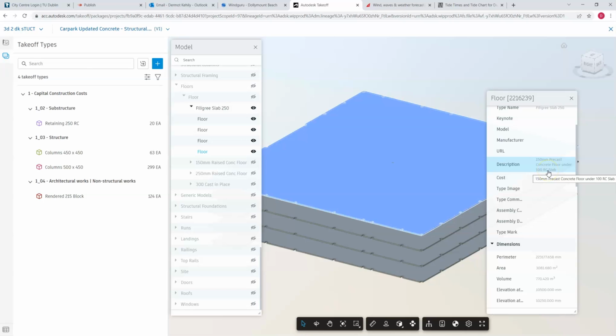So the precast floor will be, I suppose, put in place, and then over that slab, let's say a kind of a screed of 100 millimeters will be cast in place. So I guess there'll be no formwork to it from a soffit point of view to the RC slab, but there will be formwork around the edges. So we just want to, I suppose, keep that in mind.